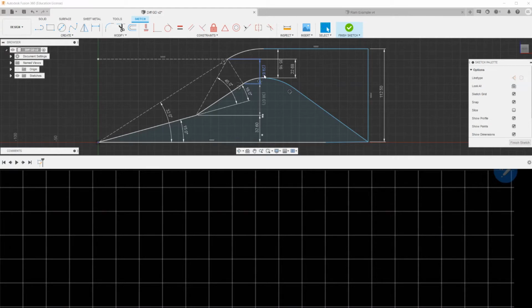This is why I say that this area here is similar to the area through which flow goes near the normal shock wave. So basically this area is similar to this area right here. It can be a bit smaller, can be a bit bigger. The variation allows us to adjust the position of shock waves, right? To have these shock waves meeting at the point of the upper edge, upper wall of the diffuser.